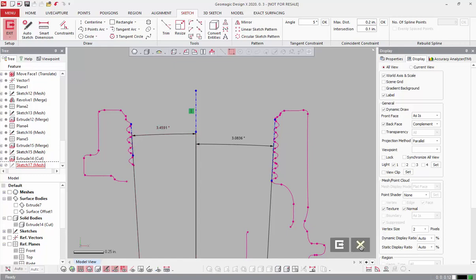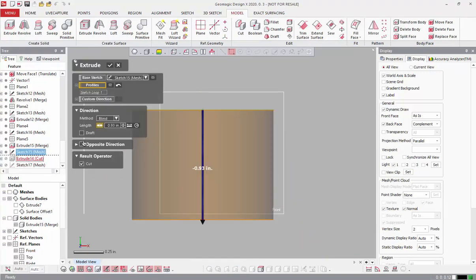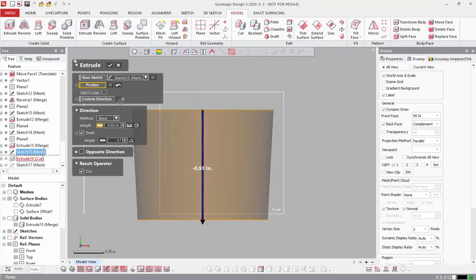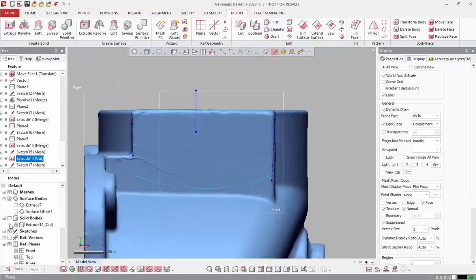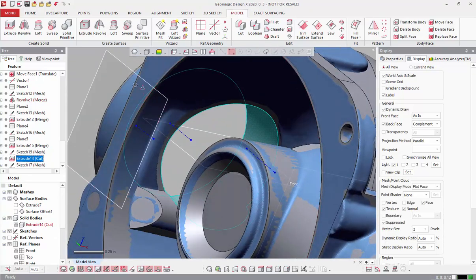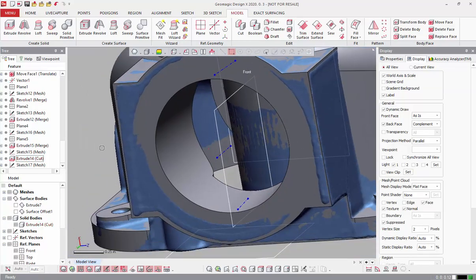So the first thing obviously that we need to do here, we'll keep this sketch and go back to it, but we will need to edit this extrusion with that, call it 3-degree draft, and see if the deviation looks a little bit more uniform there.